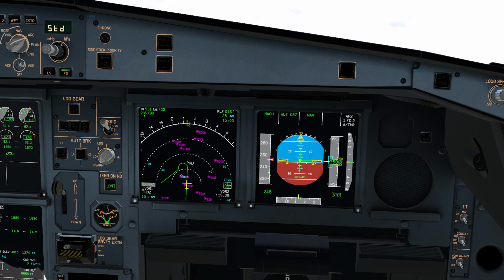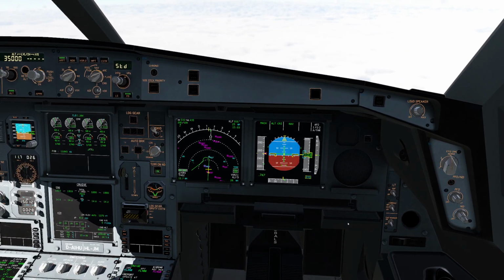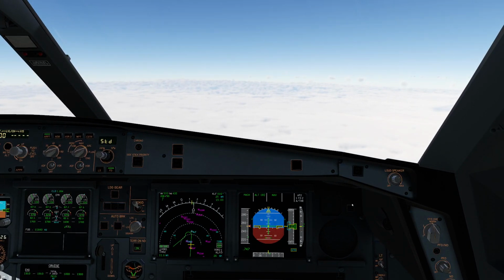When you're in idle thrust, high speeds, and with speed brake extended, the rate of descent is approximately 6,000 feet a minute. To descend from flight level 410 to flight level 100, it takes approximately 5 minutes and 40 nautical miles. So the pilot monitoring is going to ensure the MSA and make sure that we do not fly into anything that we shouldn't fly into, and carry out the ECAM actions.